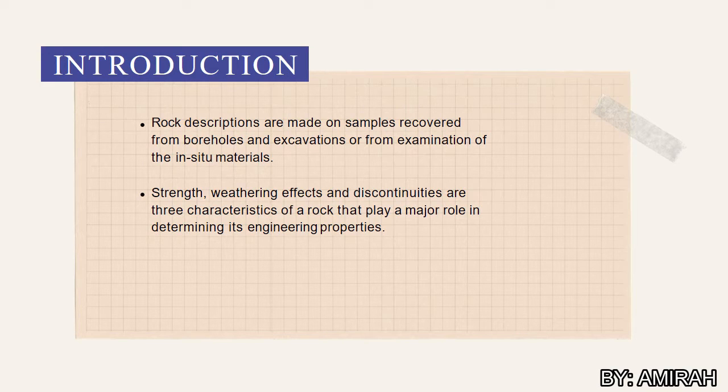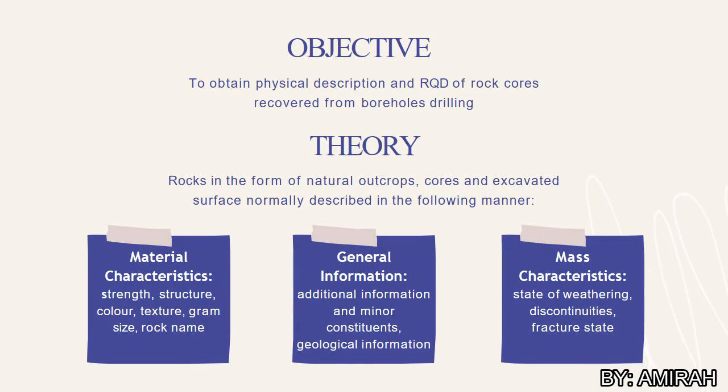Introduction. Rock descriptions are made on samples recovered from boreholes and excavations or from examination of the in-situ materials. Strength, weathering effects, and discontinuities are three characteristics of a rock that play a major role in determining its engineering properties. The objective of this test is to obtain physical description and RQD of rock cores recovered from borehole drilling.